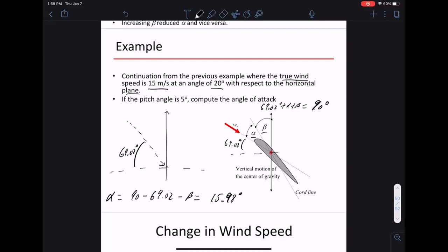As the power is changing, because the angle of attack is changing, because the angle of wind is changing, you adjust beta smoothly. You adjust beta to track the same power output, or if you want to change power output, you can change beta around. So that's why beta is easier to use. We fix the reference point, and we know that if I change beta, I'll change the power output. Then I can slowly change beta to track the power output I want. So that's a tracking problem.